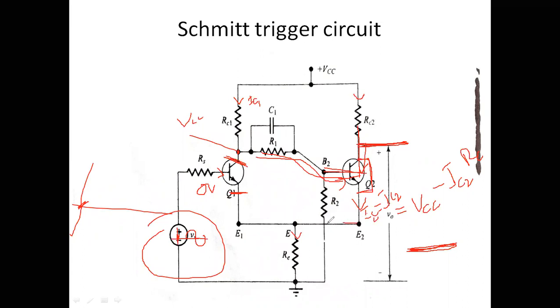Same current. This is not connected, this is an overlap. Therefore the same current is flowing through the emitter, and here it is creating some voltage drop, that is nothing but the IE-RE drop. Now if we observe this voltage for the off transistor, it makes the base to emitter. Because it is an NPN transistor, your collector is N, base is P, and this emitter is N.